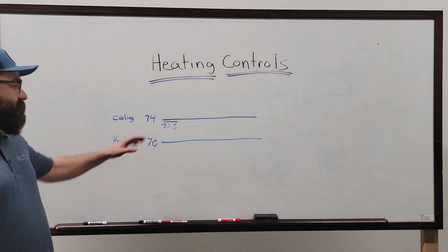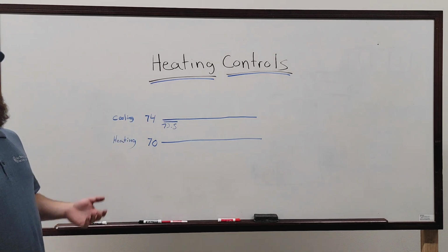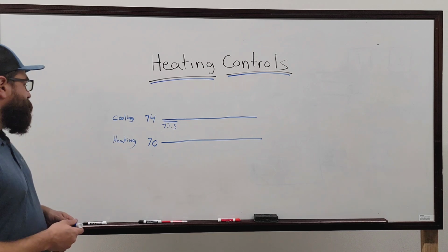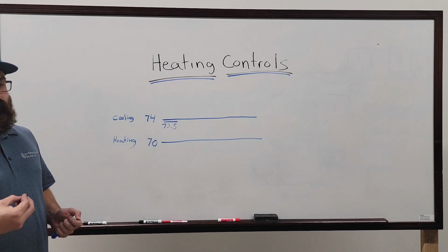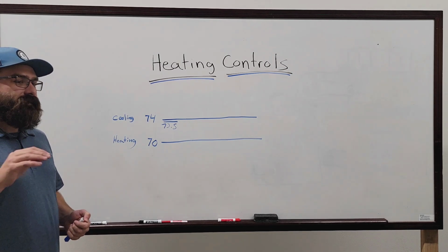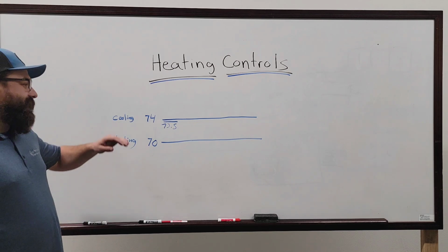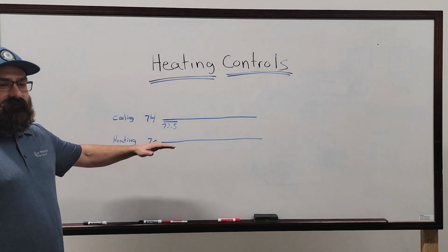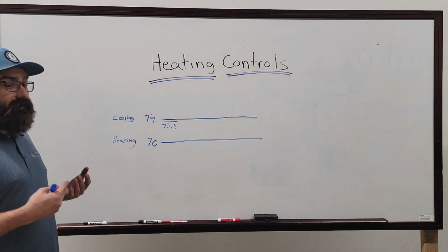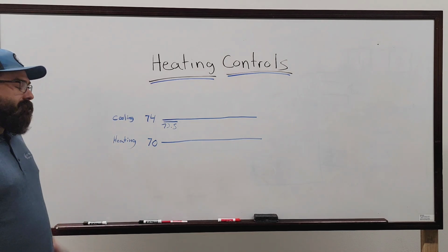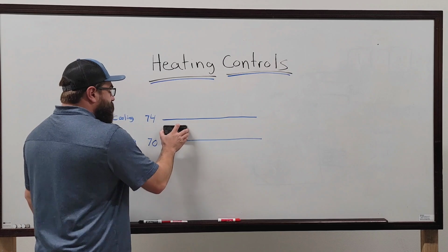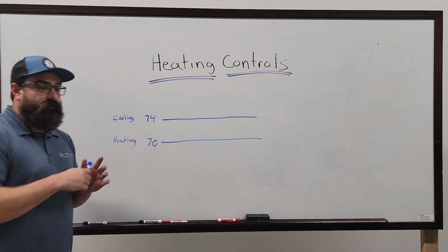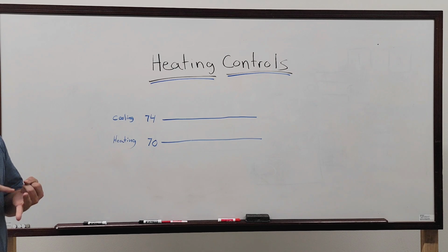I've had Distech systems that will do that, JCI systems that'll do it. Sometimes they say satisfied, sometimes they don't. It just depends. There's so many settings deep down in the core of the program that affect the way that little bit functions. It's hard to tell you that, hey, JCI every time will do this, Honeywell every time, because there's so many parameters that we can adjust to fine tune that stuff. But like I was saying, every system will have a heating and cooling effective set point, regardless of whether it's working off of a common set point, let's see, what else do they call it?